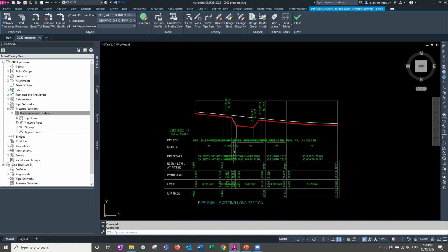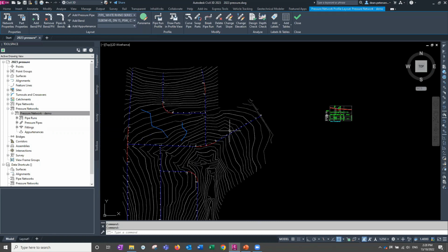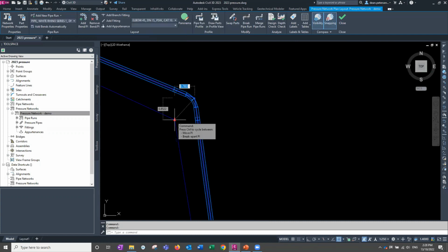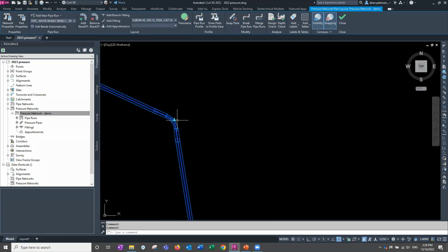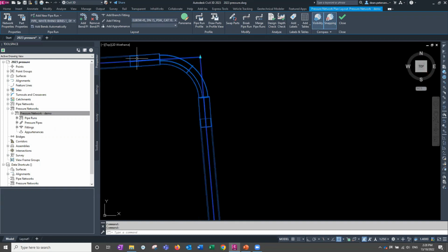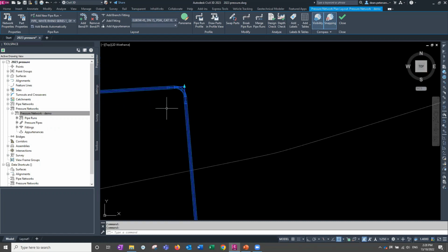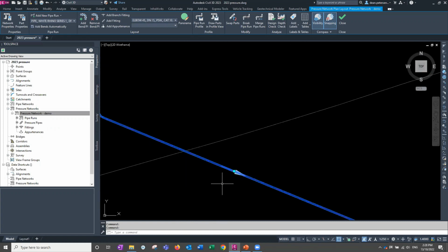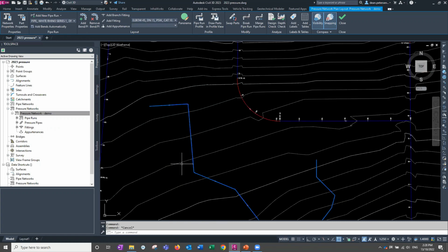along with these new tools that Autodesk have put in, including, as you may well be aware, the pipe run capability. So I pick one of these things, move the pipe run across, and all the pipes come with it. And in fact, let's change that to a 90-degree bend there, or approximately 90 degrees. It will find the closest bend, and it's changed that to a 90-degree bend. So there's some good stuff that they've done with those, and it's all with 3D objects, of course. All right, pressure pipes, those are the new things.